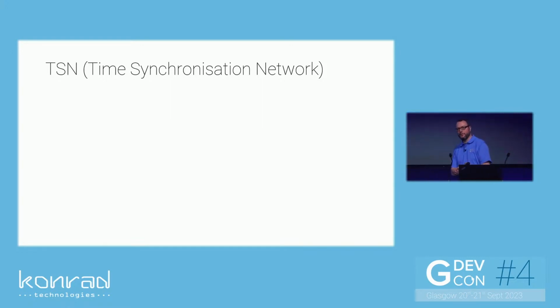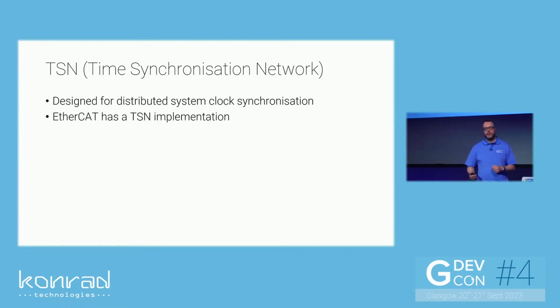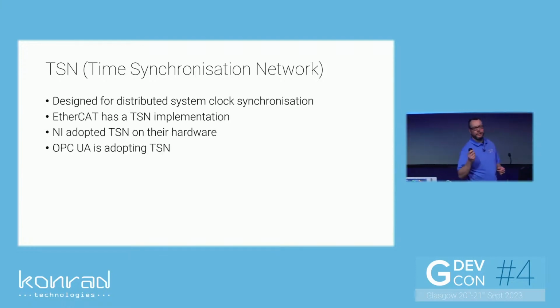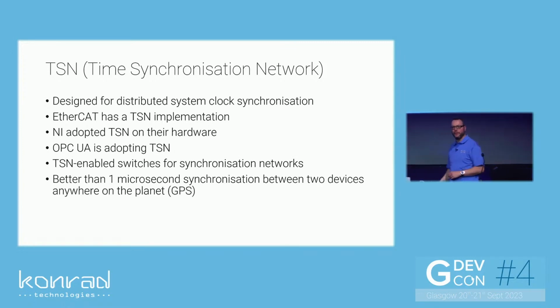Very quickly, this isn't really a protocol. Well, it is a protocol, but time synchronization. This should be really close to NI's heart, right? Because when they're selling their equipment with synchronized clocks across all their devices, it's a concept designed for distributed system clock synchronization. EtherCAT has TSN. NI adopted TSN on their hardware. OPC UA is adopting TSN. And you can get switches with TSN-enabled features in them, so you can share clock information across networks for synchronizing them. And you can get better than 1 microsecond of synchronization between 2 devices, anywhere on the planet via GPS. Use GPS as your master clock.